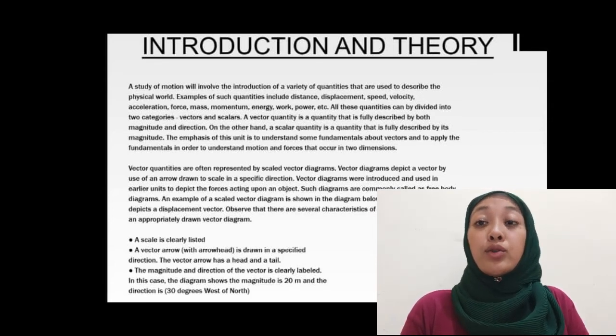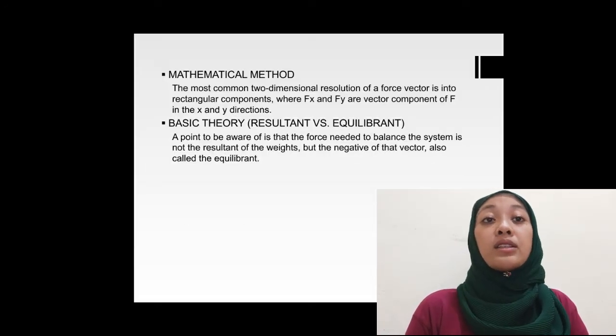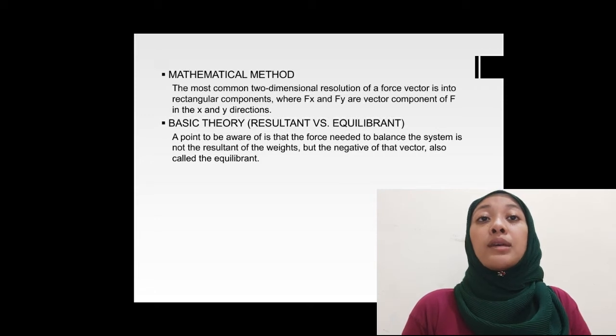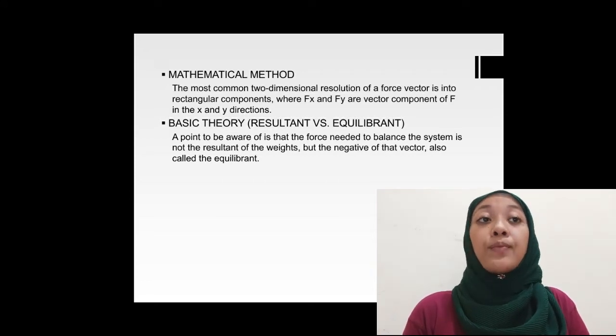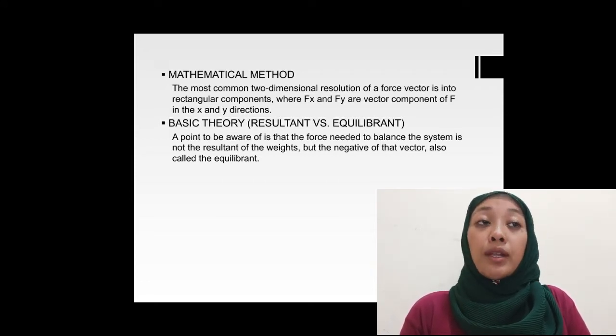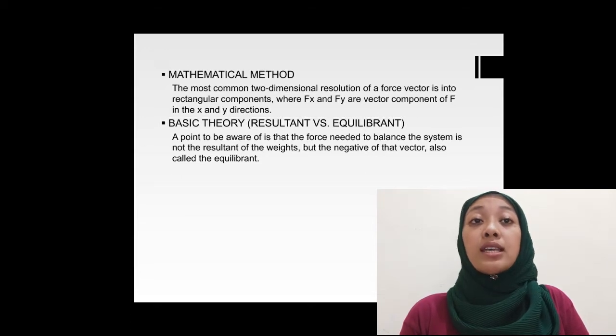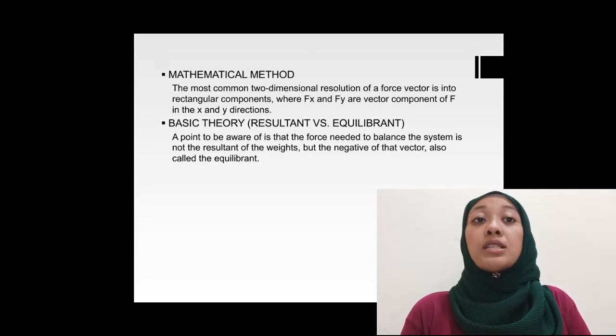The theory that we use is twofold: the mathematical method and the basic theory. In the mathematical method, the most common two-dimensional solution of a force vector is into rectangular components, where Fx and Fy are the vector components of F in the x and y directions. The basic theory is resultant versus equilibrium.